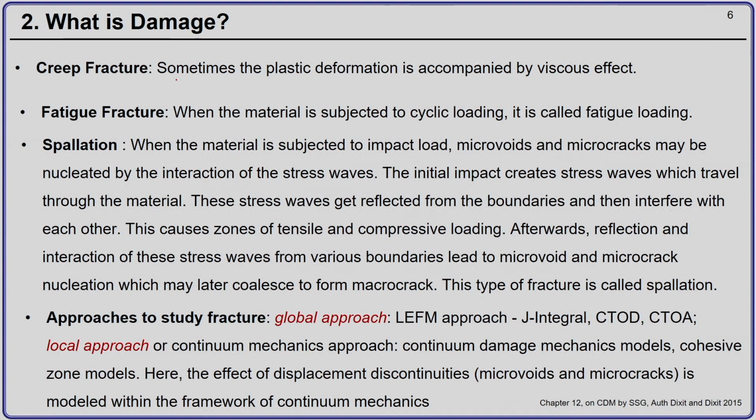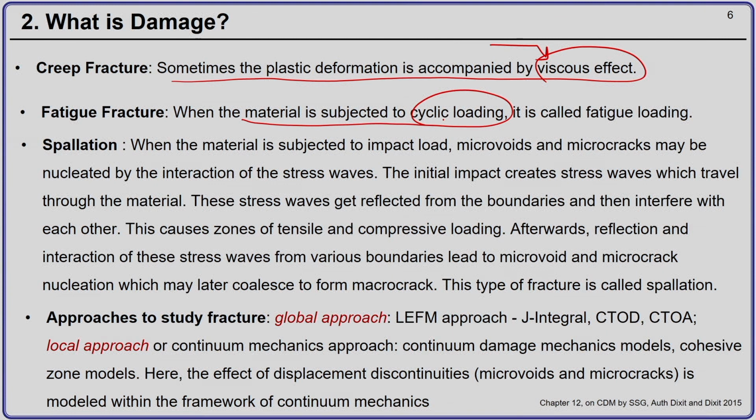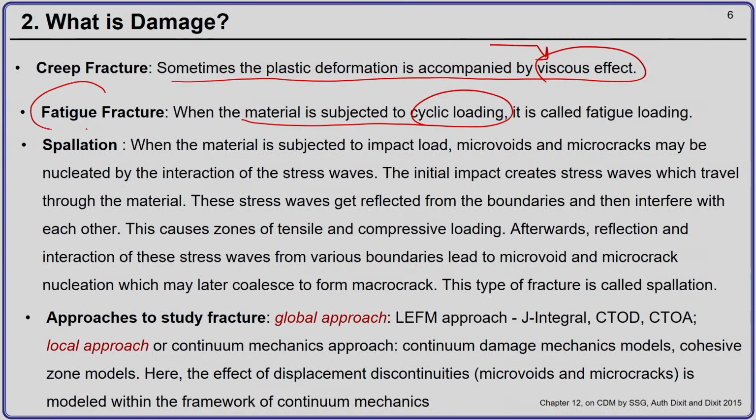So, creep fracture is when the plastic deformation is sometimes accompanied by viscous effect. So, in creep fracture you have to take into account viscous effect, and in fatigue fracture the material is subjected to cyclic loading. Just like an aircraft which is pressurized when it is up in the air and depressurized when it lands, this kind of loading is called cyclic loading, and the failure associated with such loading is called fatigue failure.